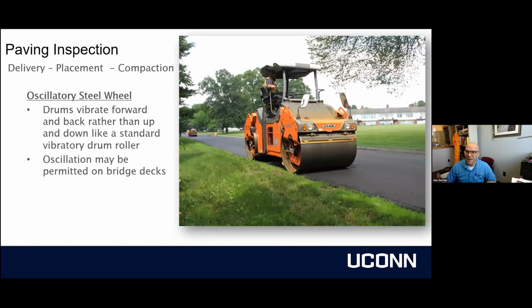The other important thing about vibration is it should not happen on bridges, or if you know you have shallow or old utilities nearby, these can break them. It's really important not to vibrate on a bridge. And if you're near an old clay pipe, you're likely to break that as well. It's pretty loud when the vibes are turned on. You will feel it in the ground nearby. Very, very forceful. It's good, right? We're trying to get density. We want that to happen.